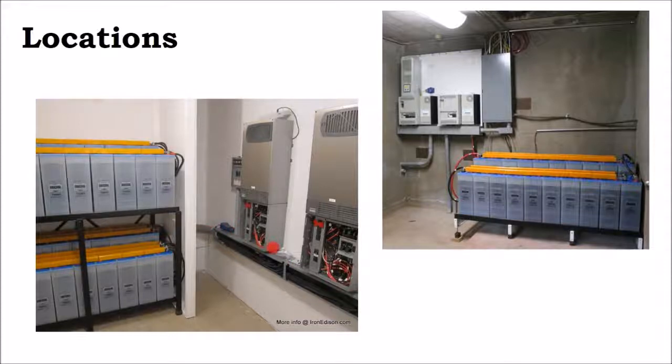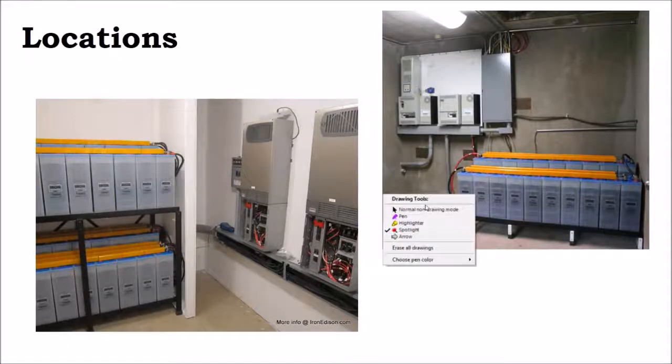What we can see is here, it looks like they're going into a PVC bend at this point. So that is a code violation from clearance, and your batteries also need to be accessible for servicing. And so if this end of the battery bank needs to be serviced, and they have a watering system, they may only need to access this end of the battery bank, but accessibility of both ends of the battery bank may also be a concern.